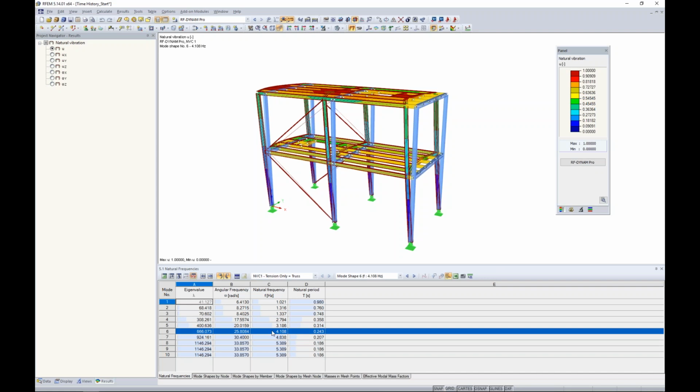So this is the natural frequency analysis of my structure. And I know that I'm going to be placing these machines on this structure. They're going to be rotating. They're going to be inducing some external excitations onto this structure. And they also will have an angular frequency and frequency within hertz as well that will be applied to the structure. So the question is, do we need to worry about resonance?